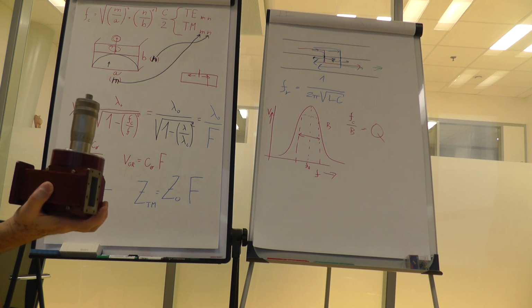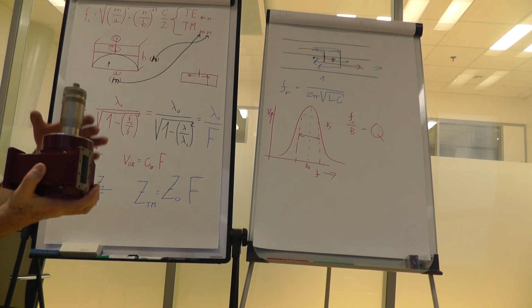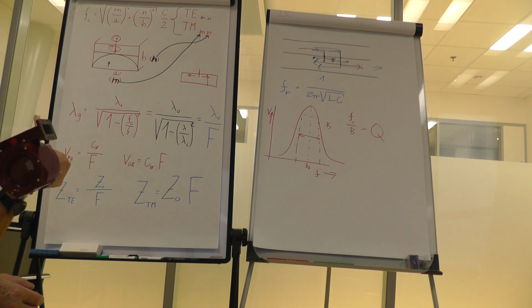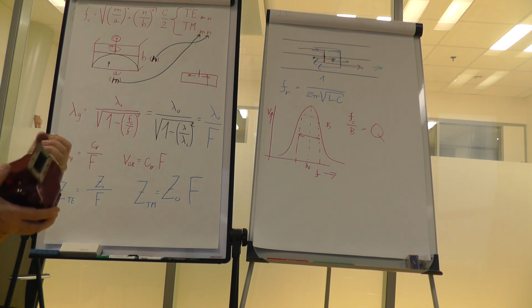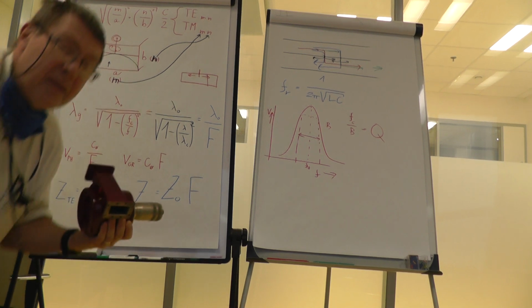So you can precisely cut a small portion of frequencies by resonators that are created as holes enclosed by metal. And that is something that you can create in waveguide technology. At this frequency band, a similar quality factor made out of inductors and capacitors is impossible.